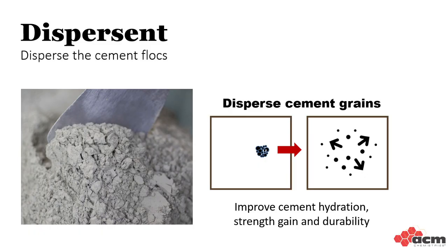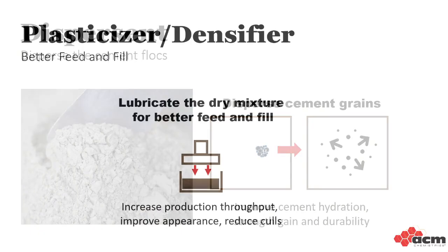If you take a look at the picture here, you can see the cement likes to form clumps or flocks. This behavior goes on even when the cement is in the mixer. Those cement grains like to stick together, which blocks water from contacting and reacting with the grains trapped on the inside. No cement-water contact means no hydration, and unhydrated cement is wasted cement. It's just filler material at that point. Plasticizers and densifiers break up the clumps, facilitate water-cement reactions, and get that cement hydration reaction going.